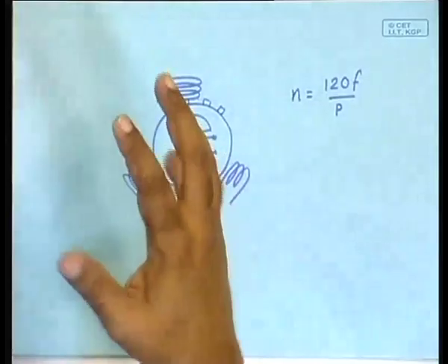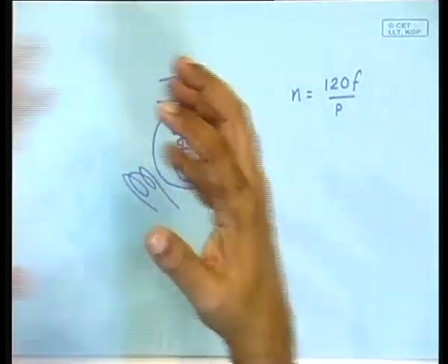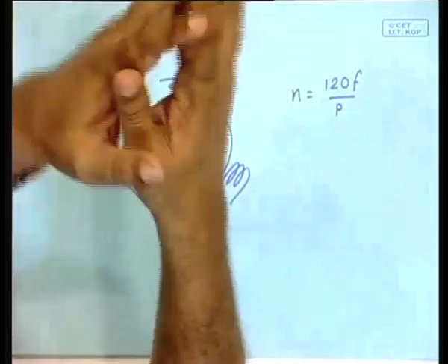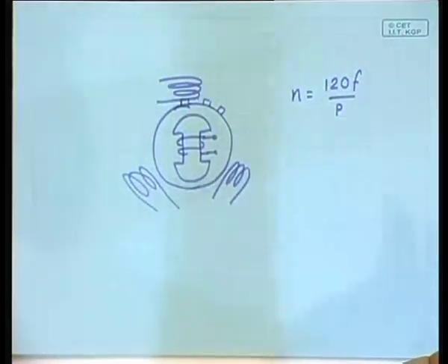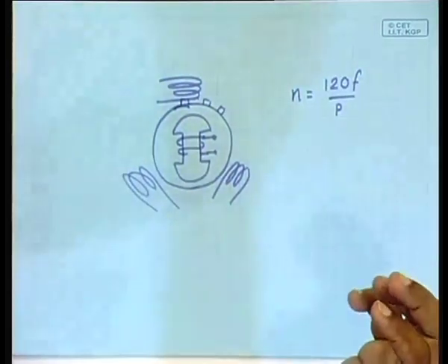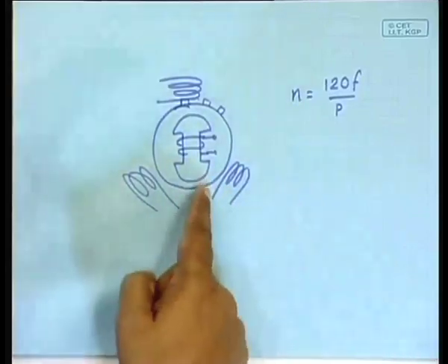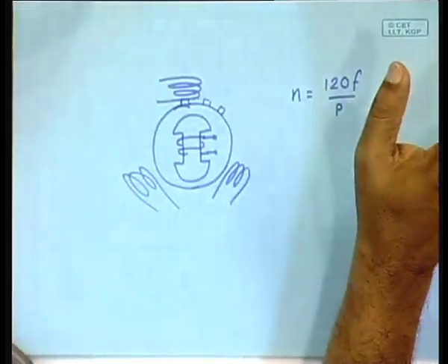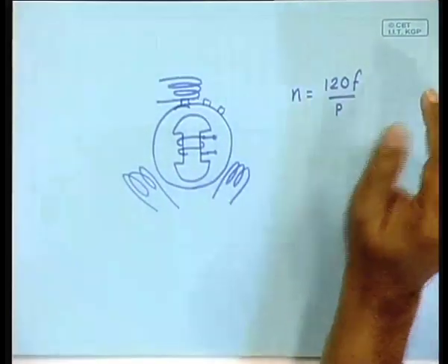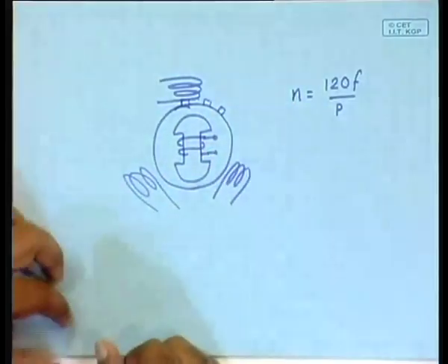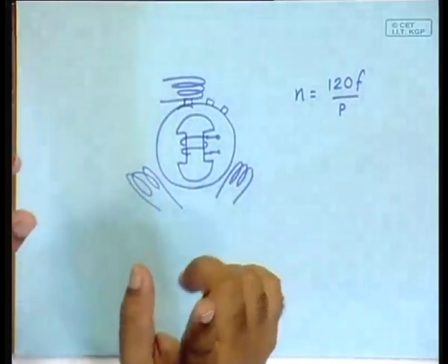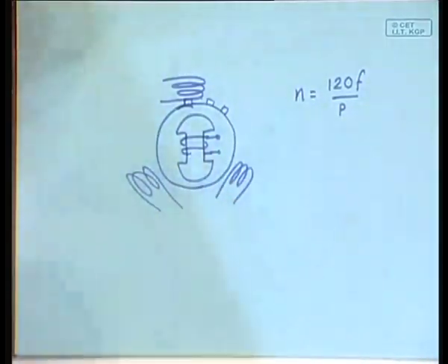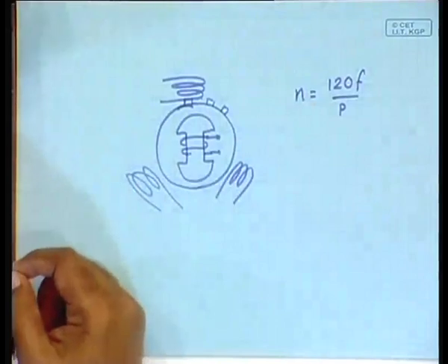that it gets sort of locked to the grid and its frequency, and so long as the locking is maintained, it cannot really rotate at a different speed. So, even if the amount of power going into the turbine changes, it still remains locked till a critical point is reached when the synchronism is lost. And that is very undesirable for a normal power plant. So, the locking ensures that even if the power input changes, this fellow will still continue to rotate at the same speed.